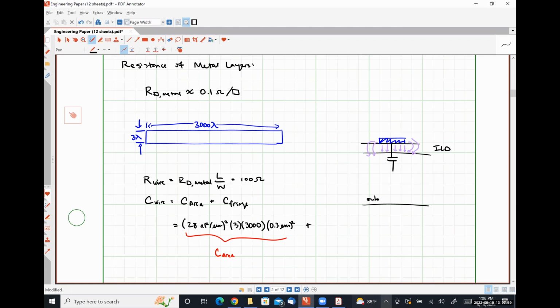So that means we're going to use the perimeter of the plate multiplied by that capacitance per unit length in order to figure out what the fringe contribution is going to be, because the fringe contribution only arises because of the edges. Does that make sense? Yeah. So in this case, as Sam pointed out, our constant here is 51 attofarads per micron.